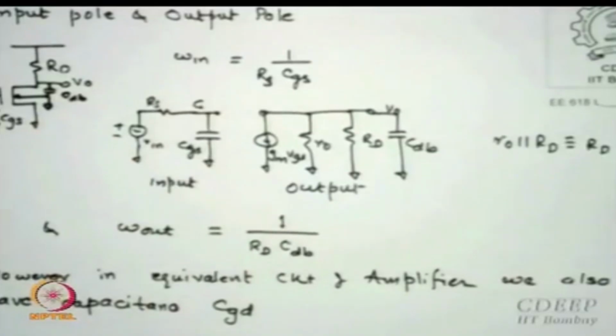The equivalent circuit of a MOS transistor we have done many days ago, so there is nothing great about it. This CGS sometimes includes CGB, because if the channel is not fully inverted, then the edge of that may give you a gate to bulk capacitance. So essentially you can say CGS includes all of it, COX plus whatever it is, and this represents CGS. As far as the circuit goes, only the value matters, so I said it is CGS which may include CGB.